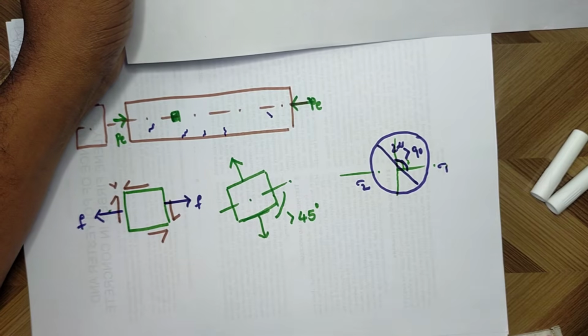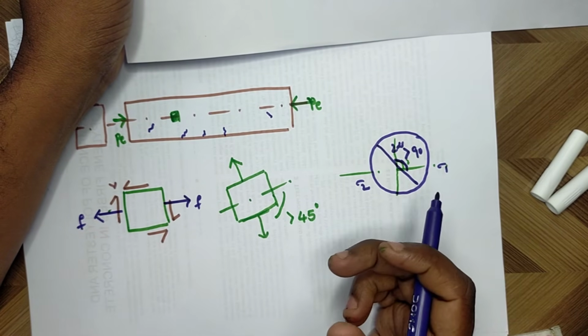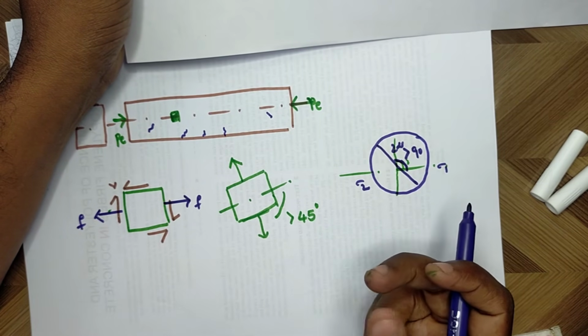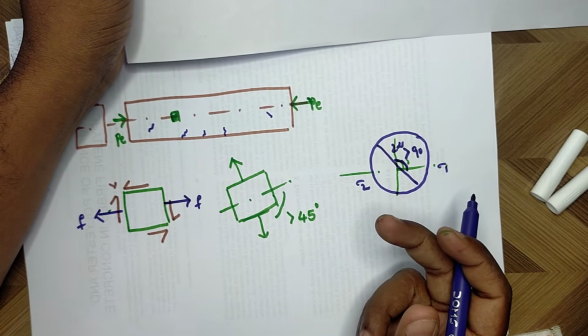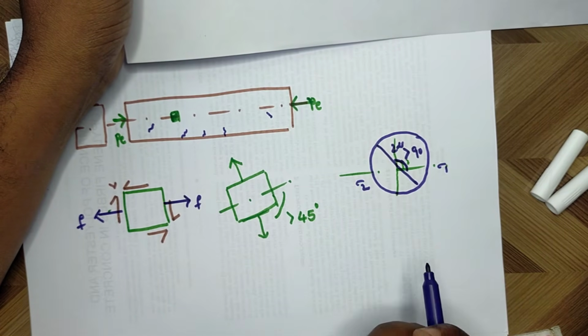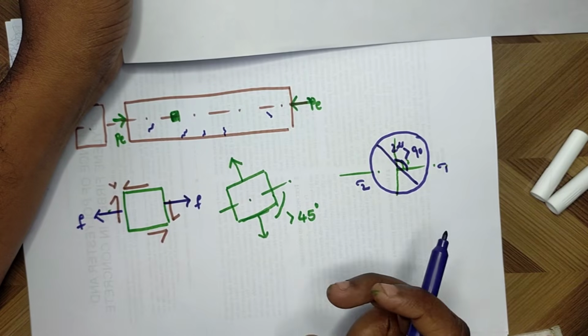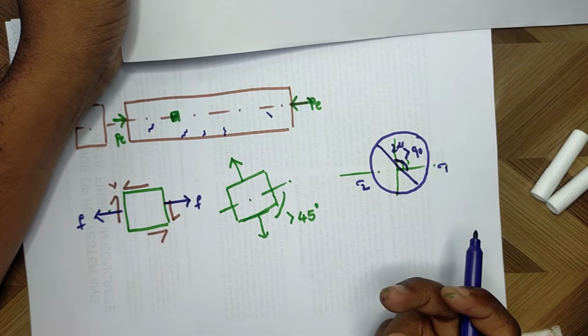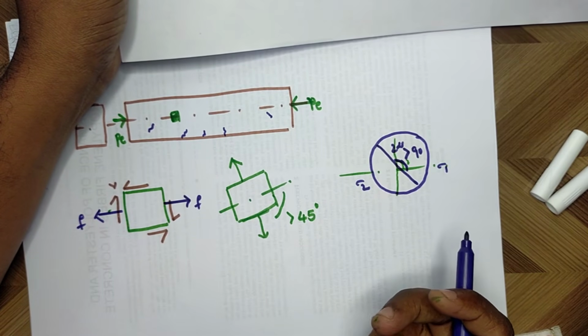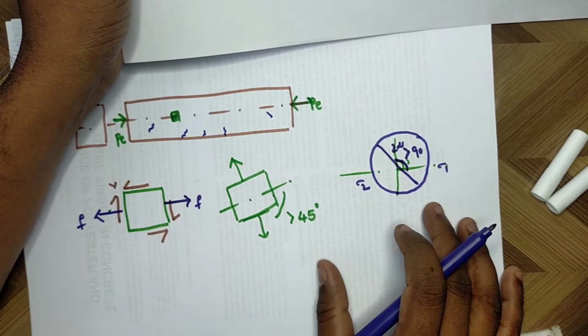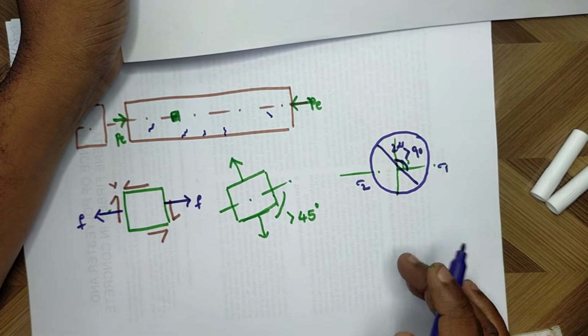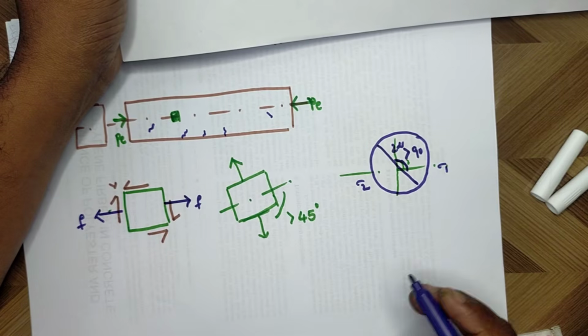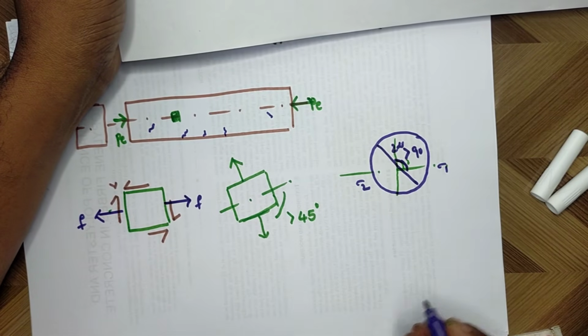After cracking, in the presence of prestressing force, the length and crack width of diagonal cracks are very low. The aggregate interlock and zone of concrete under compression are larger as compared to a non-prestressed beam under the same load. Hence, the shear strength of concrete increases in the presence of prestressing force.